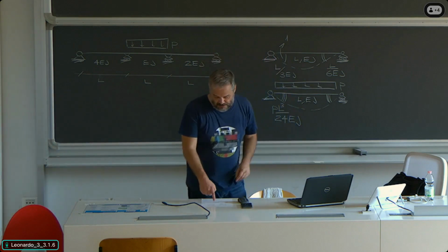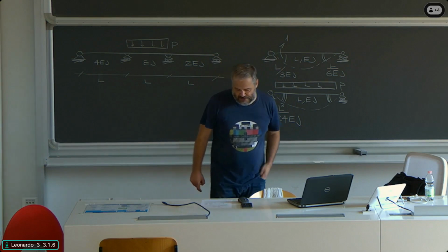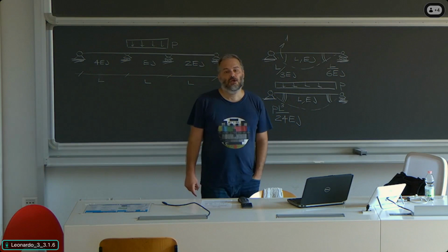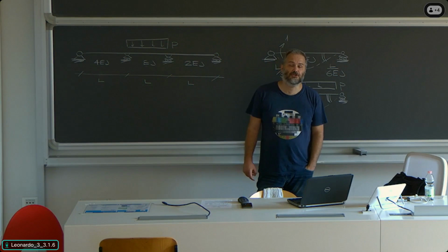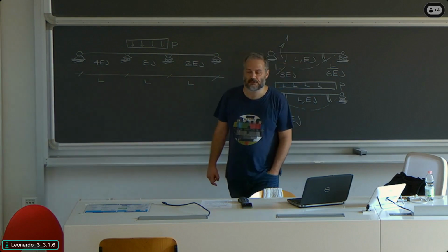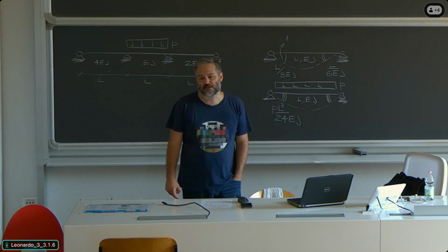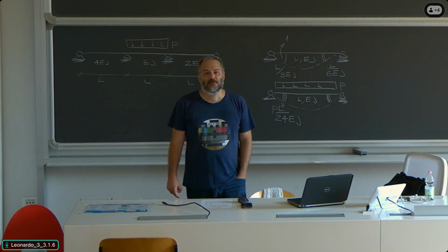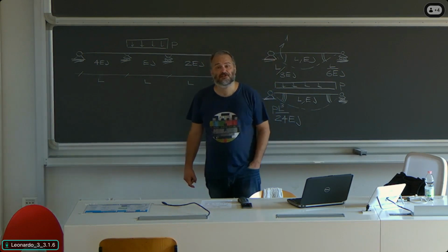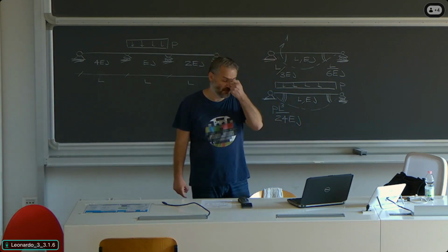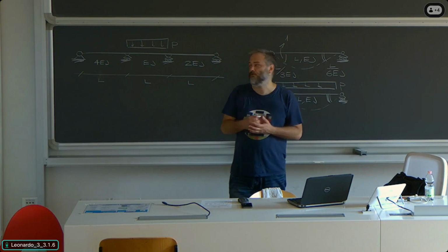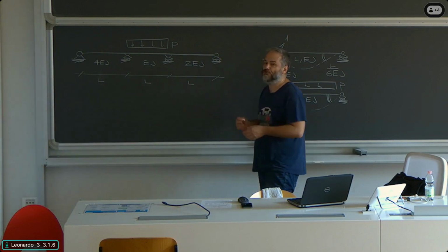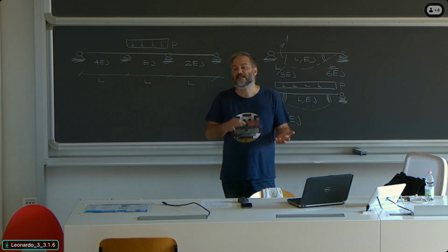Basically, since it is mentioned that the structure is statically indeterminate, you have to work out a sufficient number of internal forces or reaction forces in order to make it statically determinate. So to be able to then proceed by plotting the diagrams of the internal forces simply by means of equilibrium equations. Now, as we mentioned in class, this task is easy to perform in continuous beams because basically you have to look at continuous beams like simply supported beams or cantilevers with additional supports.